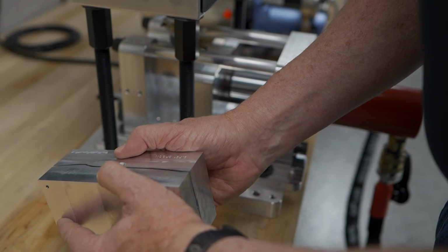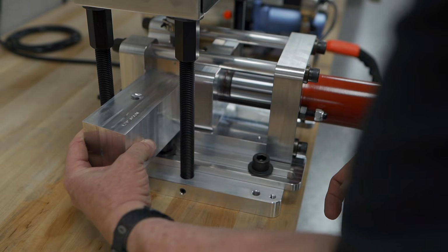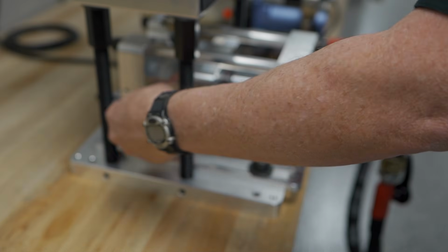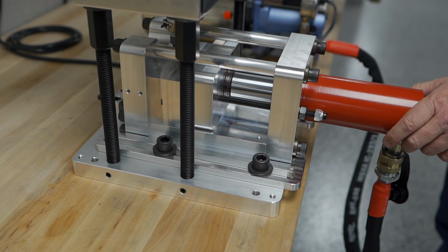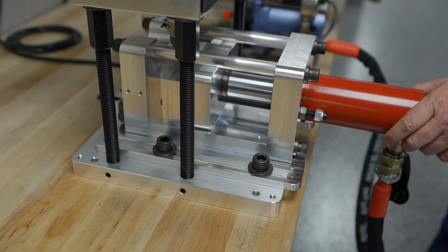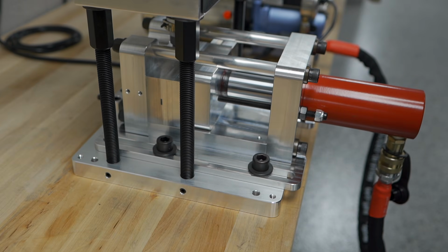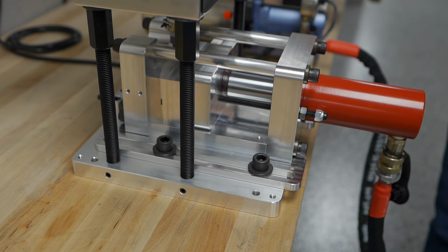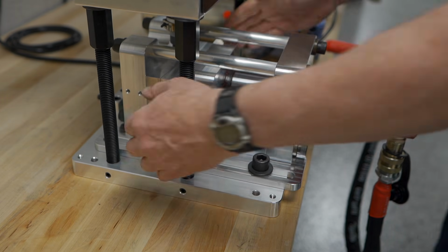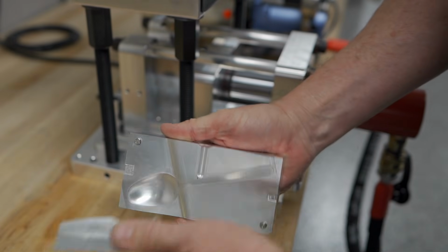Here's a close-up that will allow you to see a little bit better what's going on. Putting it into the machine, and then when he turns on the pump, you can see the ram move right there. And now it's fully pressurized, and then he can start injection right there. The packing time is to wait for the part to fully fill and to cool down so it shuts off. And then he can turn to release the pressure, and you'll see the clamp move back a little bit right here. And then he can remove the mold and remove the part from the mold.